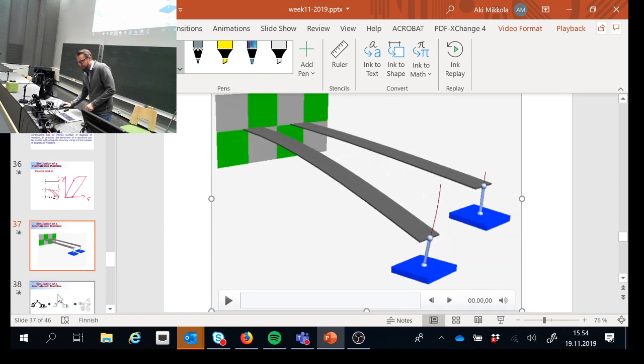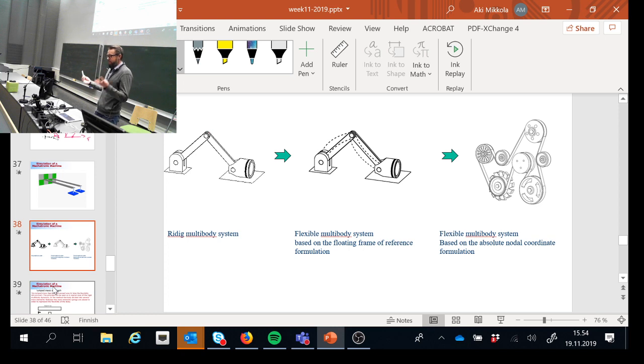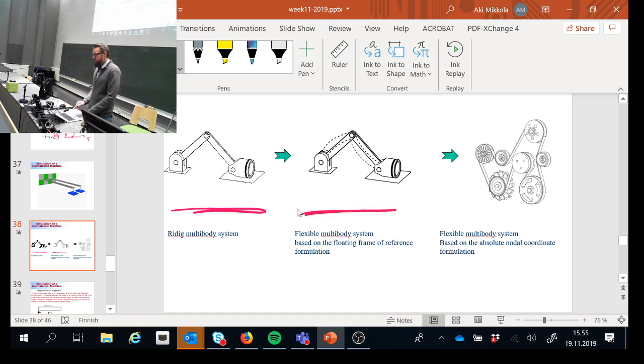It's important because, in multi-body system dynamics, everything started with rigid applications, where we assume bodies to have no deformation no matter how much force is imposed on your system. Then soon it became clear that if you wanted more accurate models, you must be able to describe deformable bodies. Then methods were introduced that were able to account for small deformation, which is typically fine when you're looking at connecting rods or simple structures, cranes and such.